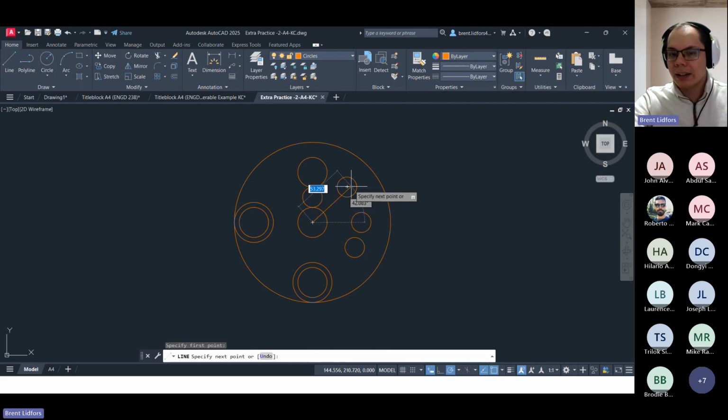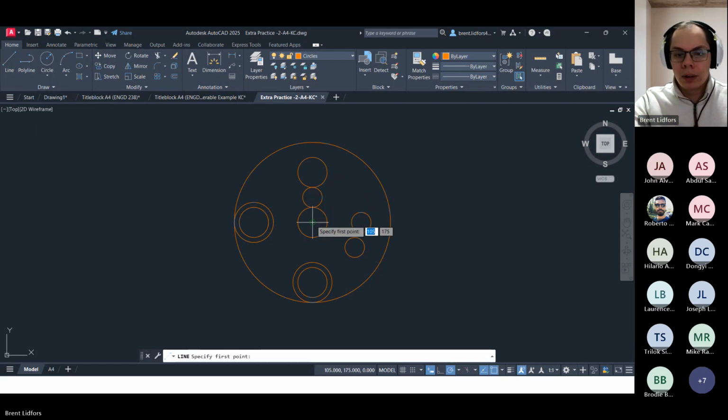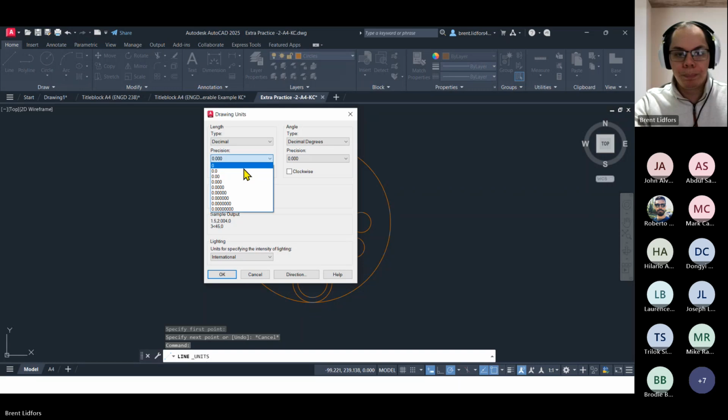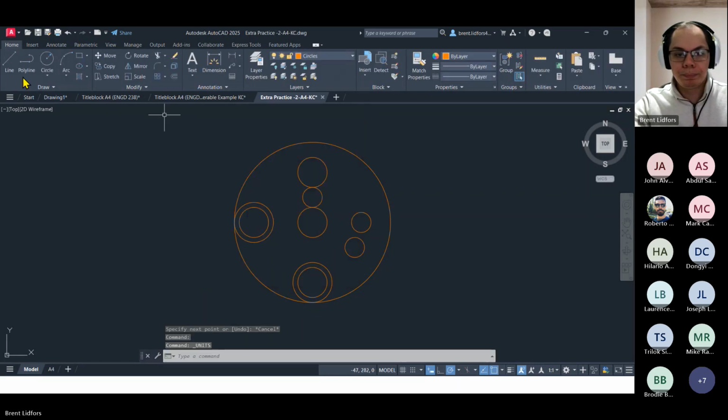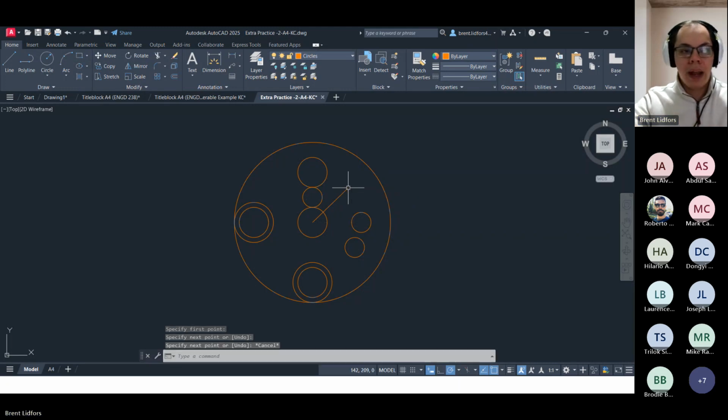If you tried to draw a tracking line prior to having this circle existing here. So if I was doing this 45-degree circle here, and if I turn my precision back down, and you just try to make a tracking line here, and you see on the dynamic input it says 45 degrees, and if I try to eyeball this again, it says 50 and it says 45 degrees, 50 length, 45 for the angle. If I click and then try to start my circle using that endpoint snap,